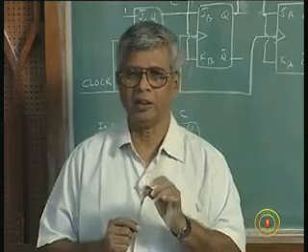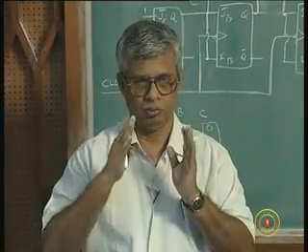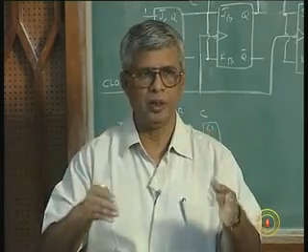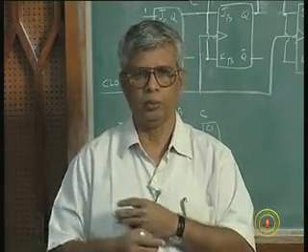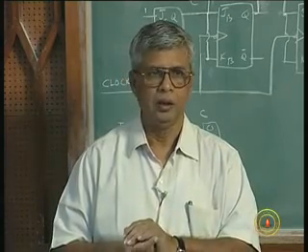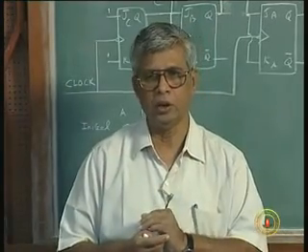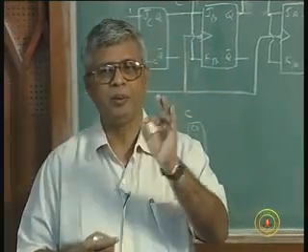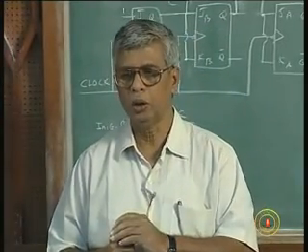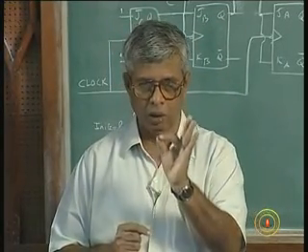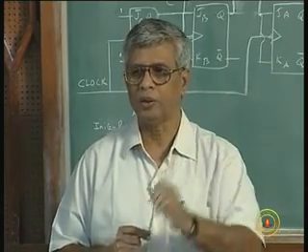in practice you never have words of 1 bit. Usually a word is 4 bits, 8 bits, 16 bits, 32 bits, like that. For example, the ASCII code I mentioned translates our alphabets and numerals into binary code. I said you get 7 bits for that, and you may have an extra bit for parity, so an 8-bit code. So I want to store the code corresponding to a particular alphabet. I need 8 bits, 8 flip flops.